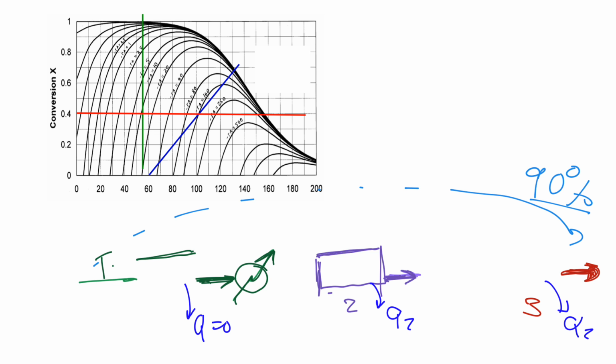You would have to specify the inlet temperature to reactor 1 to start off your procedure. So let's just say we chose it somewhere over here. Now adiabatically we are going to operate that so that it hits that maximum in the rate somewhere there. Of course, you're going to do this in Python to determine the maximum point of the rate on that adiabatic line, to size this reactor operating at the maximum adiabatic rate. That will then give me the operating temperature of reactor 1, as well as the operating concentration, which is linked to the conversion in reactor 1.